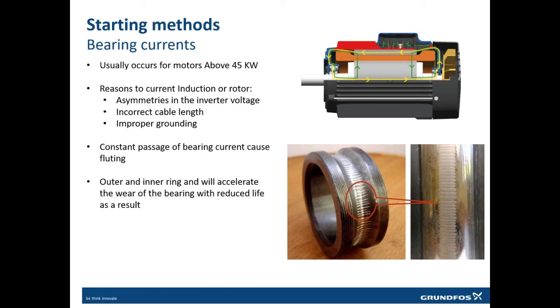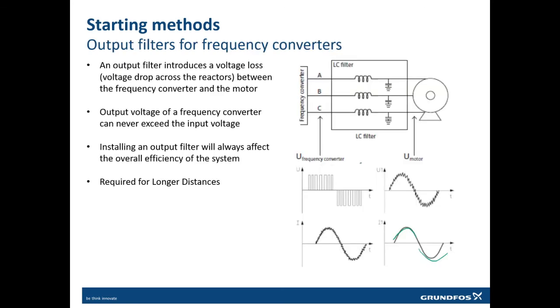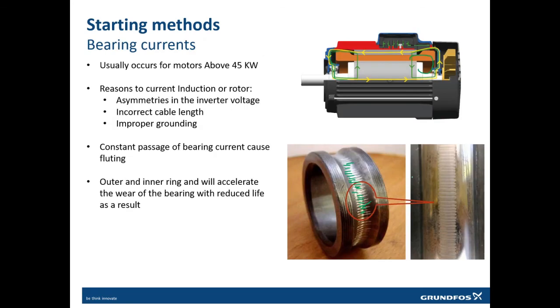Now, because of using a variable frequency drive, we tend to have currents generated inside the bearings. This is the first loop, this green loop, and this is another loop, and then there is a bigger loop of current which starts going inside it. Because of this loop, chattering happens inside the motor in these bearings, and after some time your bearings fail. Why is this happening? Because of a lot of spikes all around and a very high current.